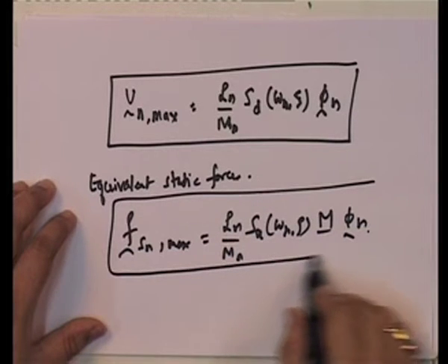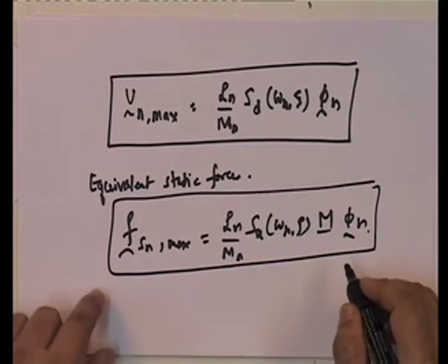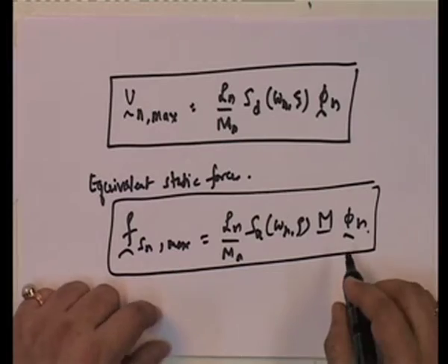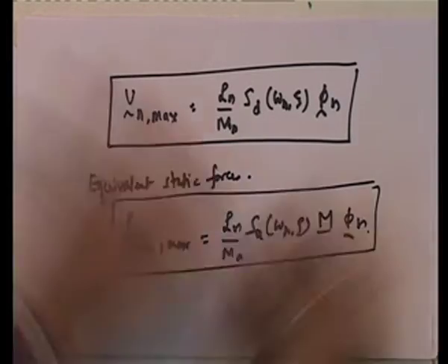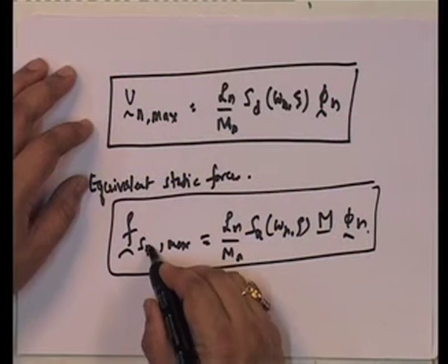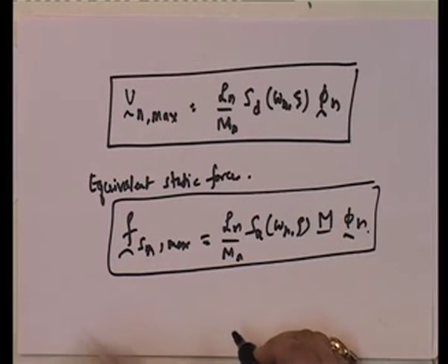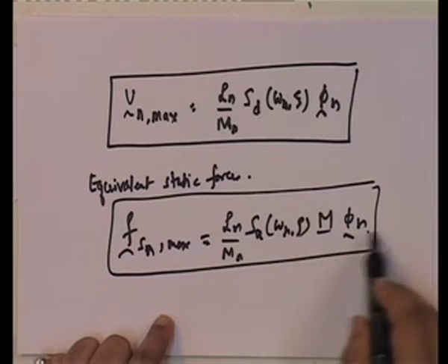These are the equivalent static forces, and you can actually apply these loads on the structure and get every other force response or displacement response or rotation, what have you, you can get all of those. Okay. Because note that in the nth mode, nothing is varying with time.